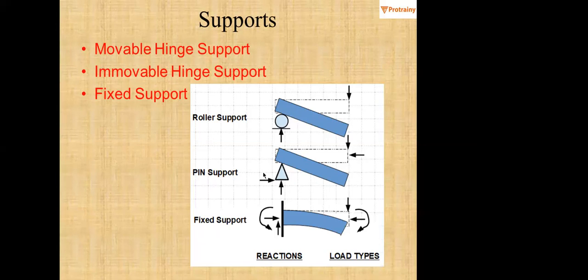So now let's talk about fixed support. After pin support, we have fixed support. What is happening now in fixed support? No vertical motion, no to and fro movement, as well as if you look at this beam carefully, it is not allowed to rotate here. It is not even rotating. So I am obstructing its rotation along this direction, right? So what is happening? We end up with the moment in opposite direction. In order to obstruct this rotation, you have to provide a moment from yourself.